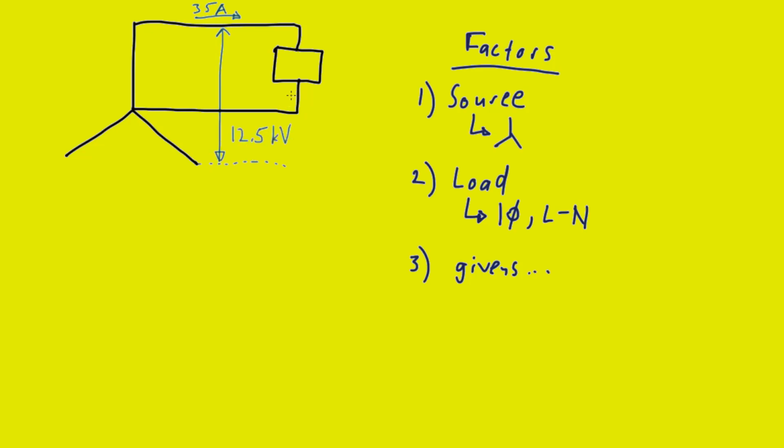A good way to see that phase current matches the line current is to notice that the current is not diverted by any other branch along the way to the load. In our last example, it was very clear that the phase voltage and the line voltage match, and now we're dealing with the current in this particular situation. With this Y connection, it can be a little confusing to see that, so a good way to help visualize that the phase current and the line current match is to visualize it in opposition to the way a delta connection might look.